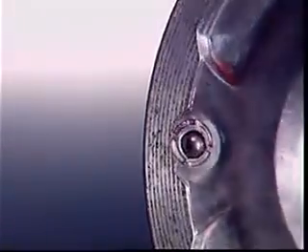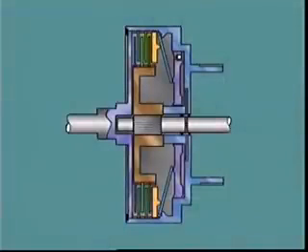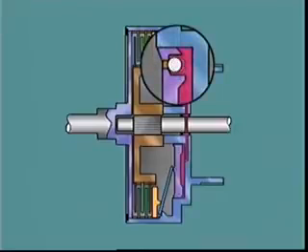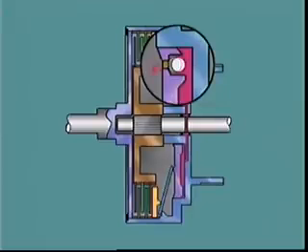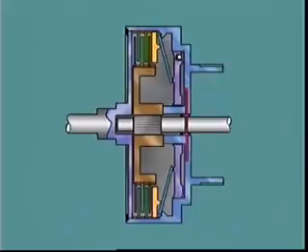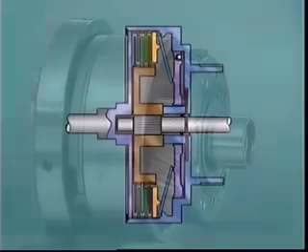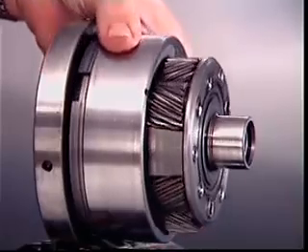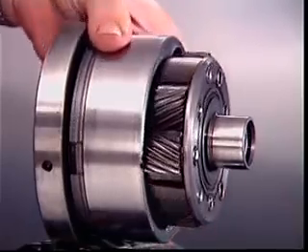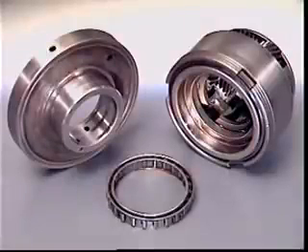This can be prevented by a pressure relief valve in the piston. It is normally a flat reed or ball check type, which is easily closed by the apply fluid. On release, the valve is unseated by the rotation of the assembly, letting fluid escape. One-way clutches are used in the gear train to allow rotary motion in one direction only. They simplify the hydraulic and mechanical control of the members.